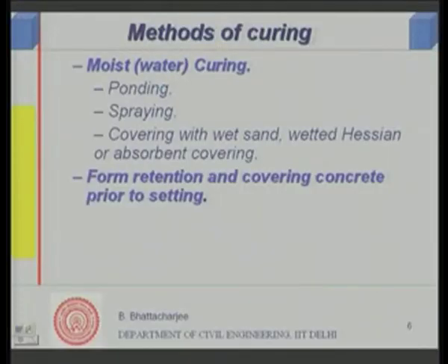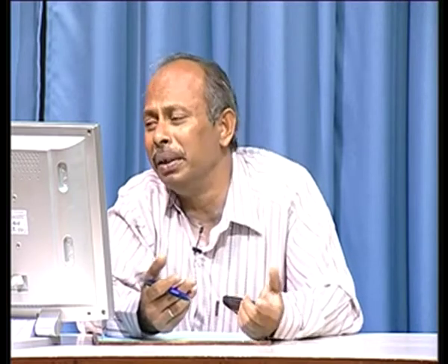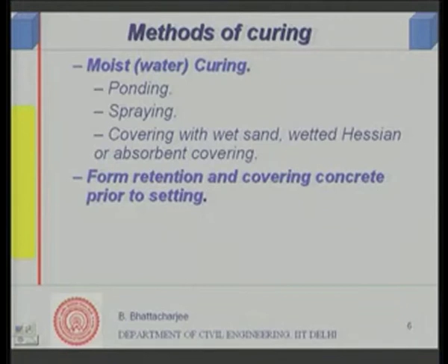Now, that you can do provided you have sufficient water available. If you do not have water available, then what do you do? At least you can cover the concrete. First of all, curing does not start until the concrete is solid, after which you start sprinkling water.